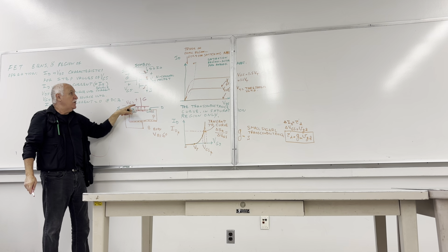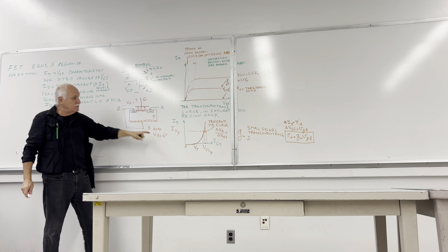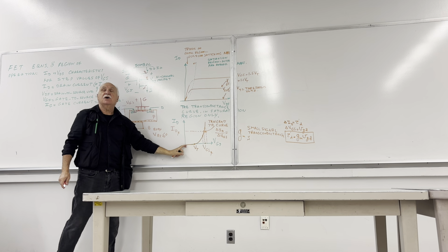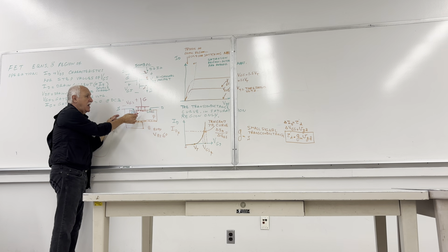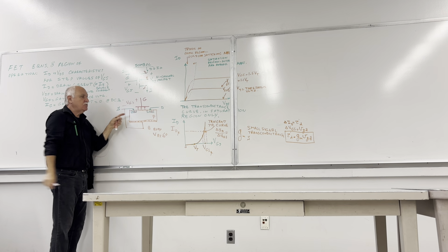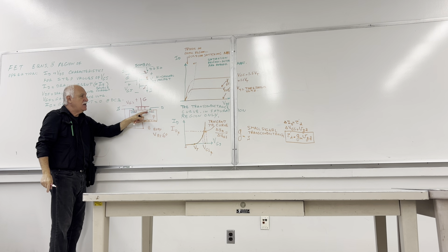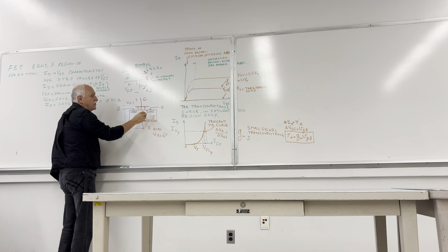But without the electric field or insufficient electric field, that means insufficient gate to source voltage, this phenomenon will not happen. Electrons will not be enhanced. It will be blank. If it happens to be blank, you have N, P, and an N. These two look like reverse diodes.